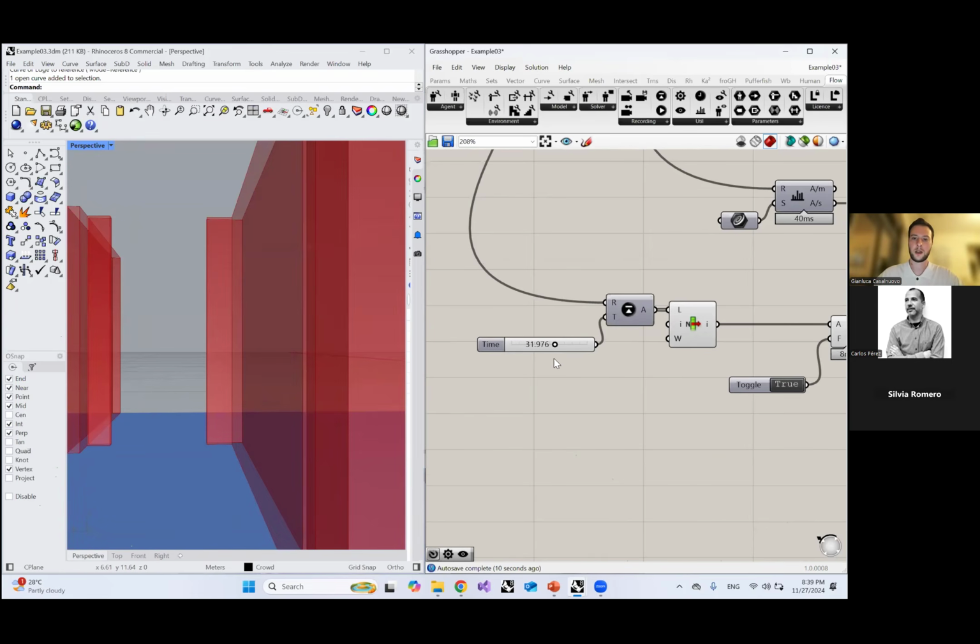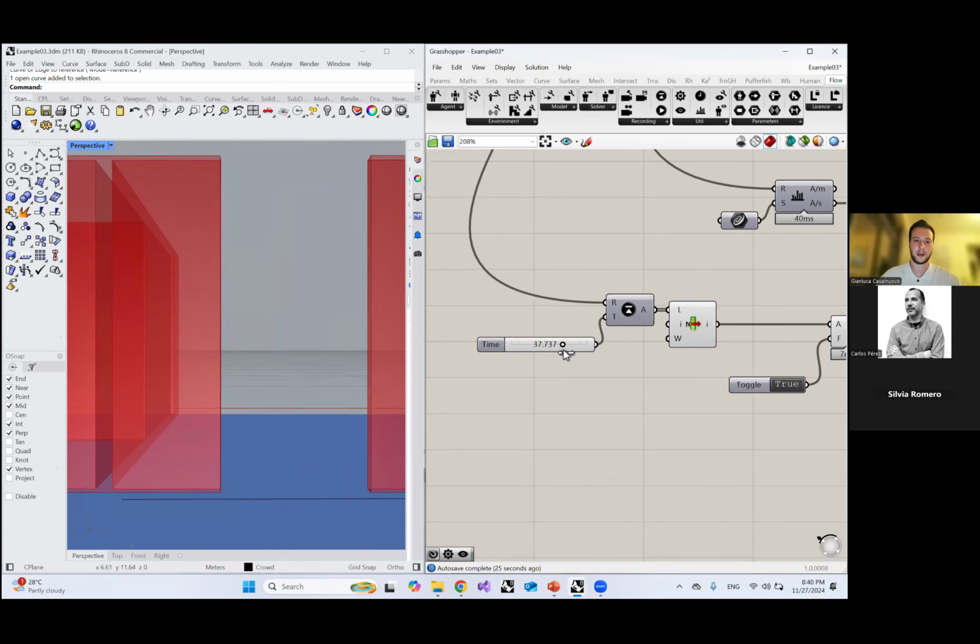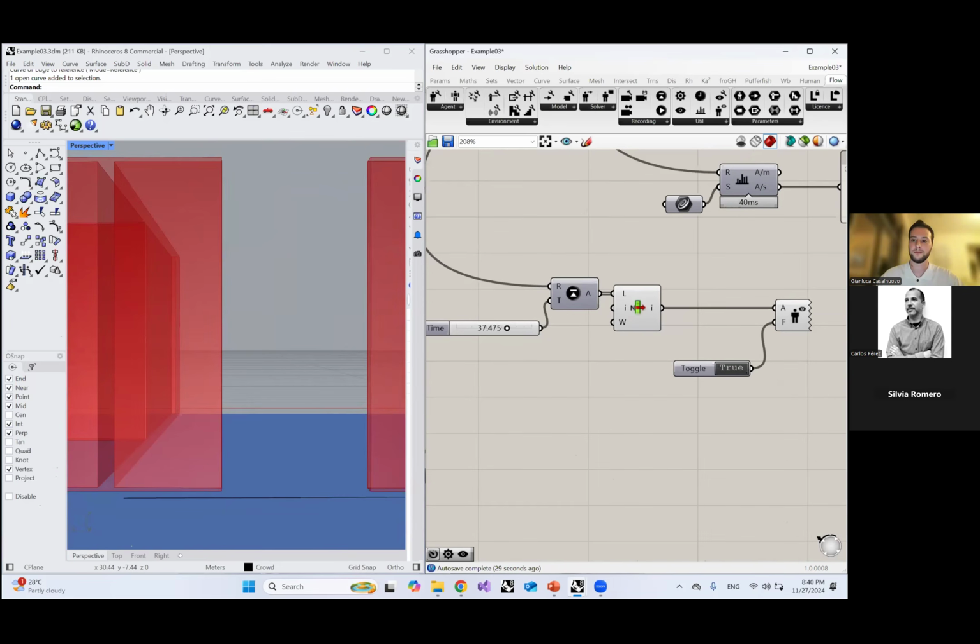This is actually not very suitable for evacuations, but more suitable for crowd modeling, because during evacuation agents usually bump into each other, so it's pretty chaotic and you are not able to see very nicely. But just imagine that you have a full model in Rhino with nice materials in render view. Then you can actually check how people experience your design, right? Let's say, for example, that you are designing a stadium and you have standard seats and VIP areas. With this component, you can check how a standard or a VIP experience is in your design, or if people bump into each other, and different things.